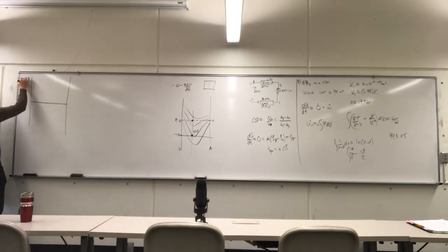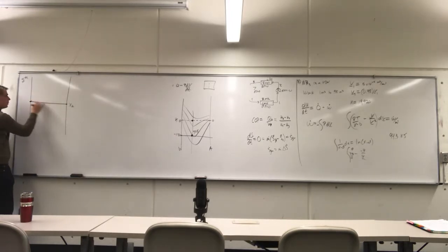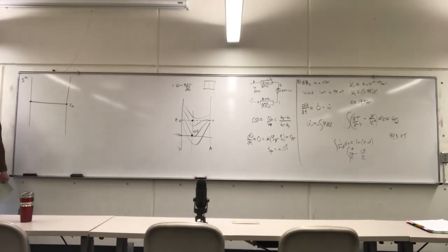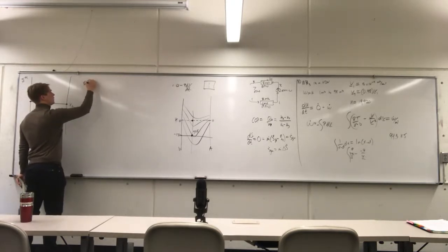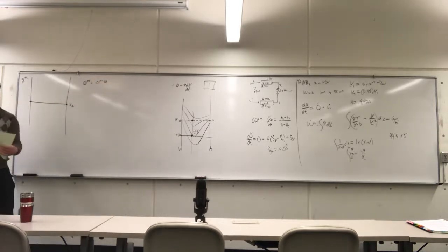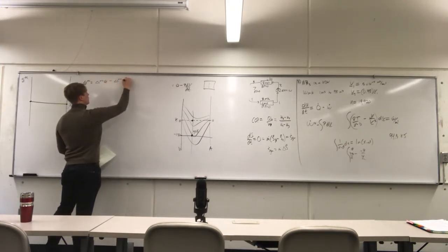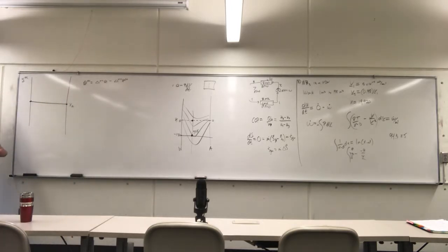Right, so what we talked about is if we have a system here, where in this case we are looking at the excess entropy of mixing a component as a function of, let's say, x of A. So we have an A-B mixture. Now, there is no excess entropy or any excess property of a pure fluid, right? Because there's no way that a pure fluid can behave any differently than how the pure fluid wants to behave. Now, the excess function is simply the difference between the real change of a property when you mix it minus how that mixture would behave if it were an ideal mixture.